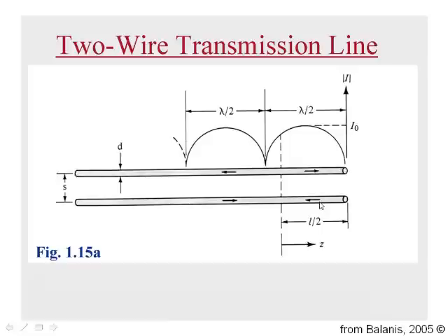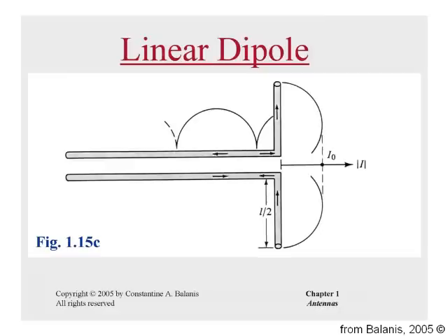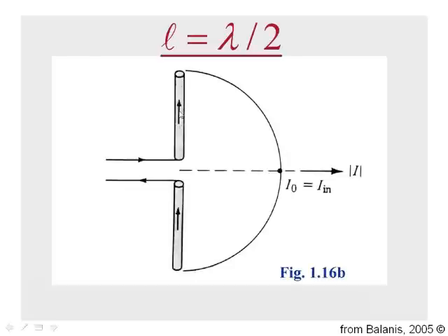When I take these wires and peel them apart, what I'll then have is currents that flow in the same direction in space. Even though relative to the wire end they flow in opposite directions, from a standpoint of which direction they flow in space now, because I peeled these wires apart, they are flowing in the same direction. And so the current standing wave on this antenna is null here, it's positive, but it's also positive right over here at this driving feed point, and then it drops back down to 0 again. That's the standing wave pattern of current on a half wavelength dipole.